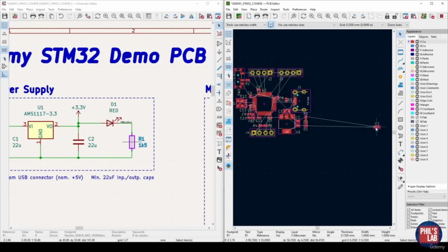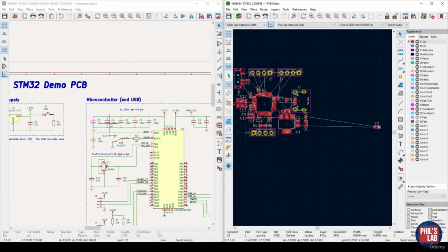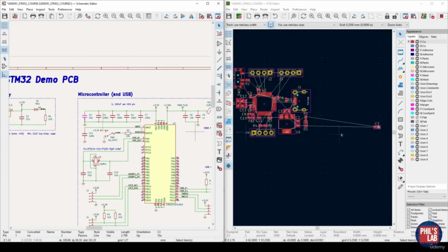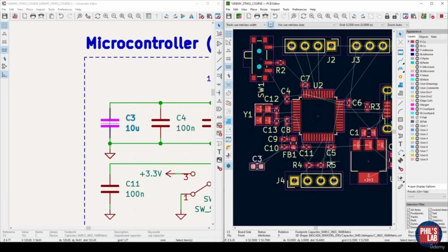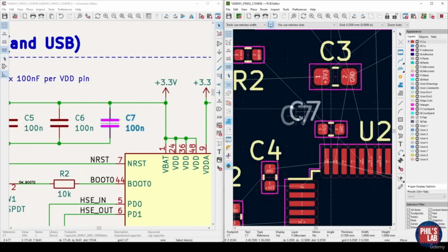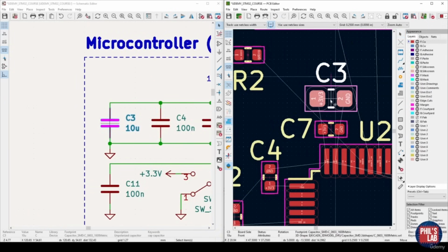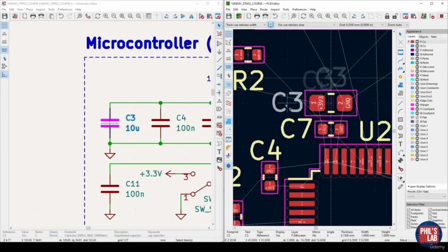You can see I have one last component floating around here. And if you remember back, this is the bulk decoupling capacitor for the microcontroller. And this, as I said before, can be anywhere close to the relevant IC package. Because our power source is here, the furthest distance away is somewhere up here, so this is typically where I'll place my bulk decoupling. So if I just rearrange this a tiny bit, I will probably put it somewhere up here, like so.